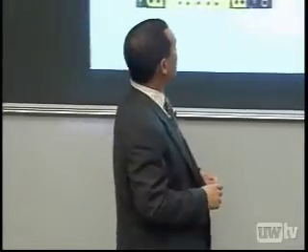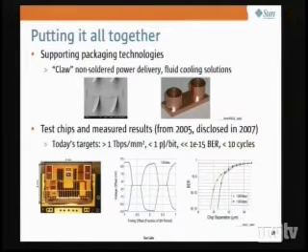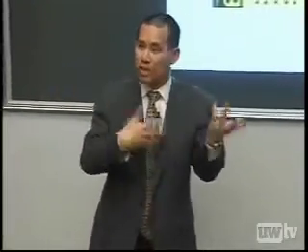Okay, putting it all together, here's some work that I wasn't directly involved in but helped out on. If you have a lot of chips that are arrayed out in this proximity grid, the question is, how do you put power in them? Well, you could solder them, of course, but once I've soldered them, I lose the argument that it's a high-yield system, because once they're soldered, I can't unsolder them. And so you have this known good die problem.